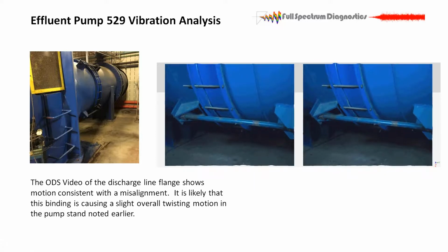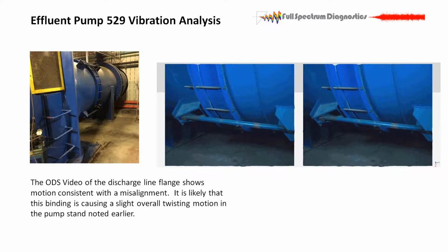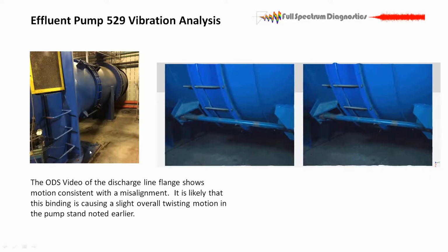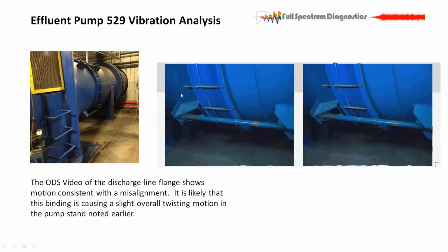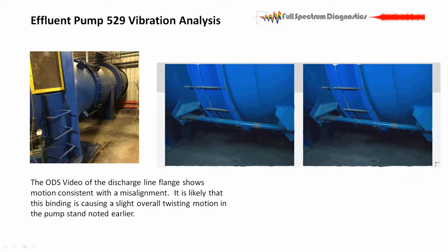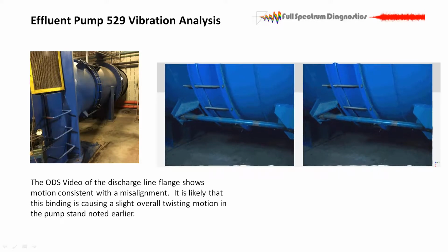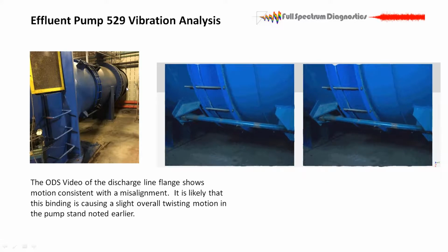They just had a problem historically. They made the pump a little too short and the line a little too large, and they couldn't get it to line up. This is one of their resolutions. They drilled some holes through here, made them oversized, and put this threaded rod in to try to draw in both ends. Really, this is a much stiffer structure than this side. So what they're doing is distorting and putting loads into the housing on the pump side instead of on the discharge flange side. And you can see the motion in these two.